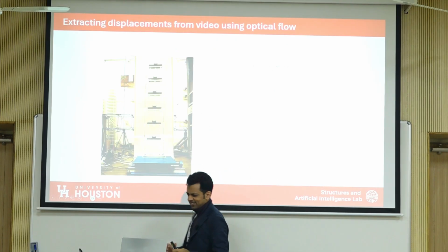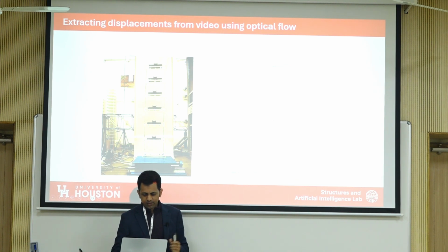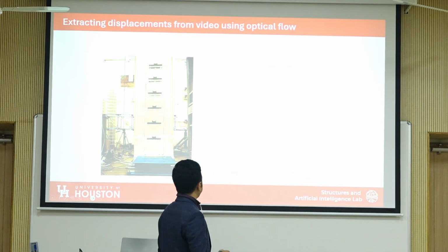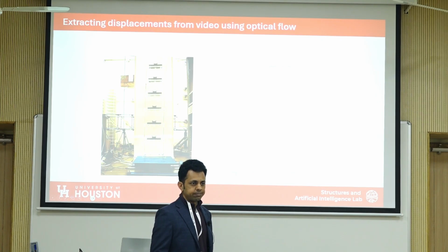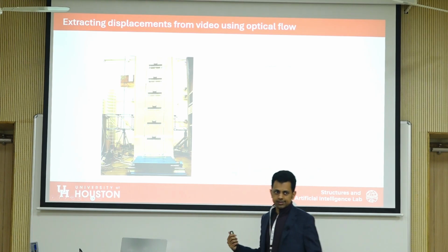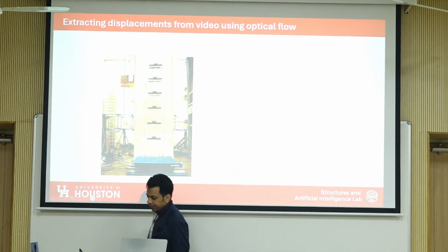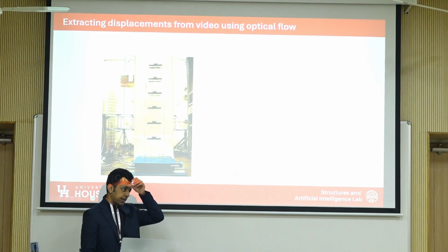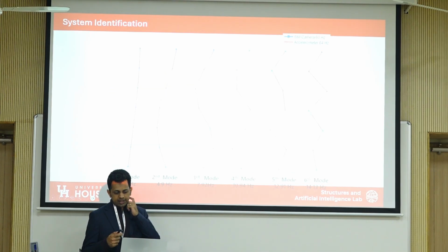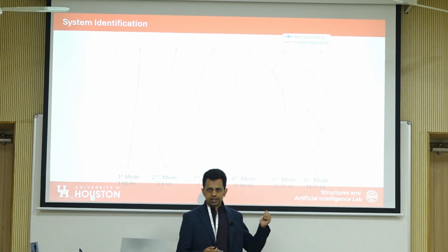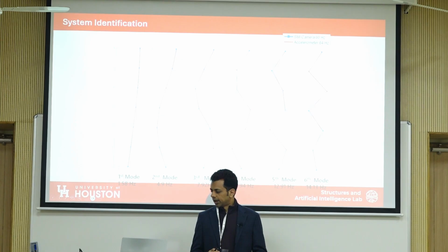Now it's clearer, right? I think when I played it, maybe I compressed it. That's why. But you're getting this displacement signal, and you can use that for any sort of processing. What the camera is useful for is getting that signal. So even if it's a static displacement, you can measure it, which is otherwise pretty hard to measure. The extracted information can be useful for getting dynamic properties, and it can be very accurate.